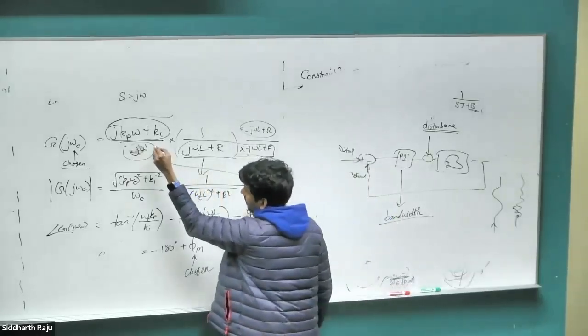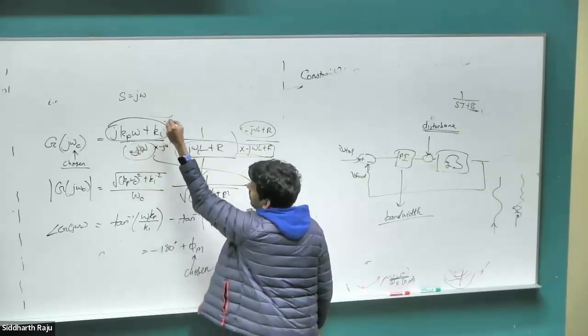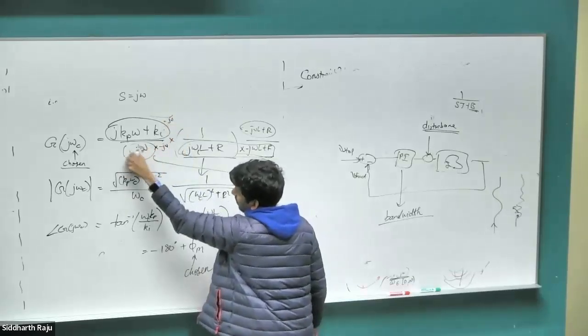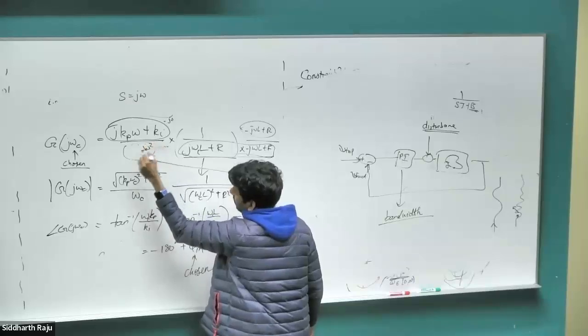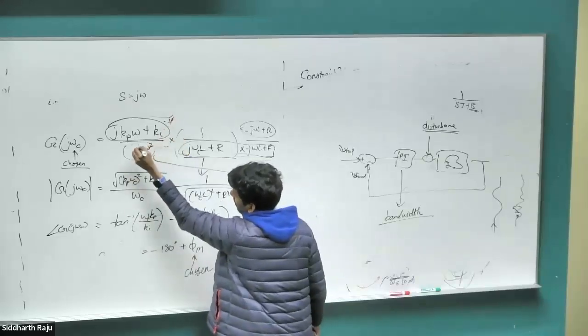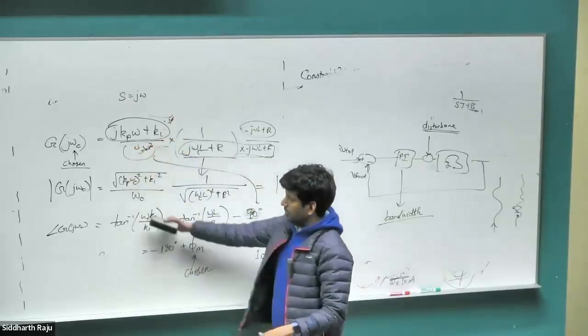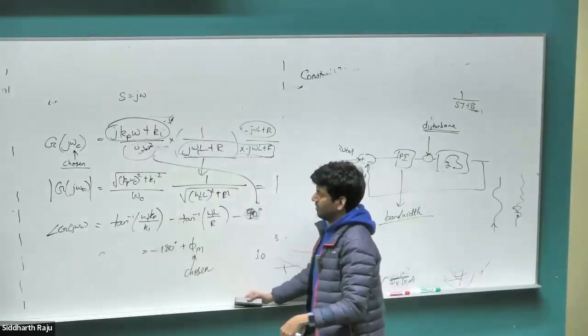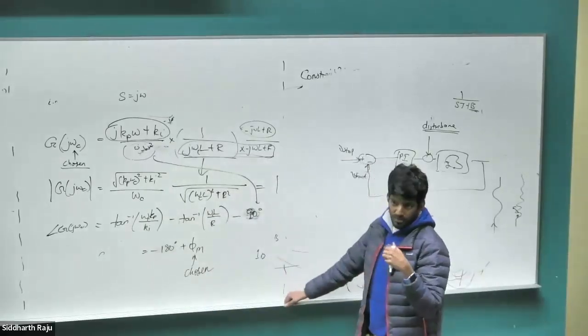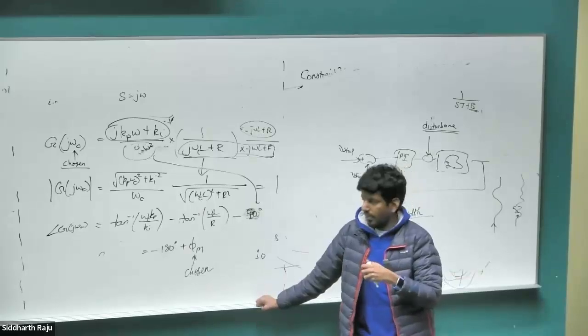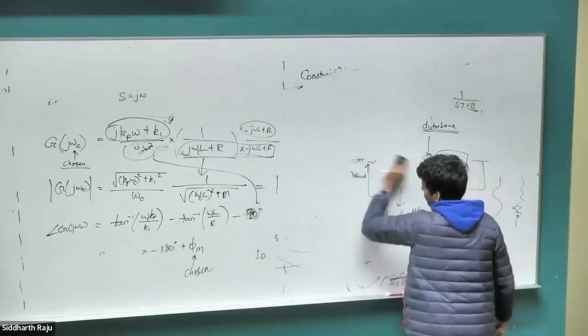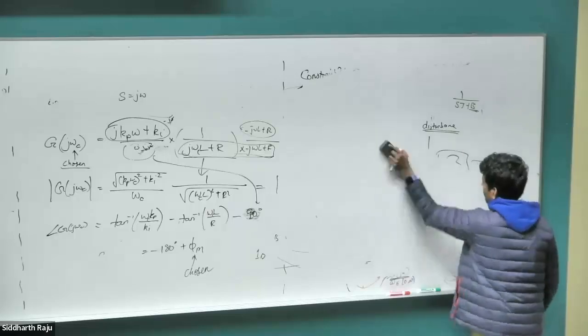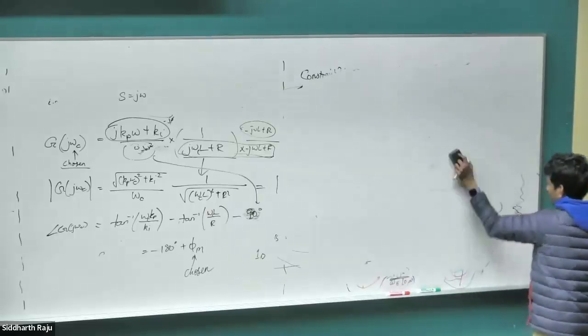And so, again, take the complex conjugate, negative j omega. Negative j becomes positive 1, you get omega square. And then you have omega cancels. So the magnitude is just omega, and the angle is minus j, which is negative 90 degrees. Any questions? Okay. So now that we have designed our current controller, we can control our current.